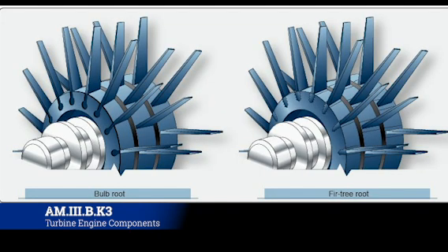Okay, so this is another thing that's kind of important for you guys, because you will take apart a turbine engine while you're here with us, and so I want you to see how these blades actually connect to the engine itself. There's going to be a rotor disc that's spinning around, and those blades will slide in and out of that rotor disc. In terms of maintenance, you're going to have to check these for dings, nicks, and so forth, and then blend those blades out so they are nice and smooth and able to move the air and compress it as needed.